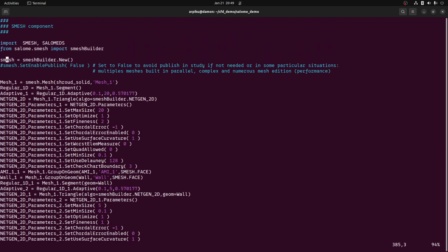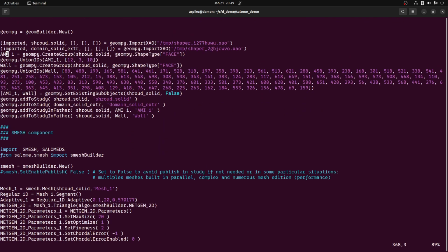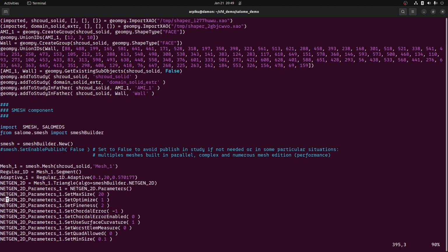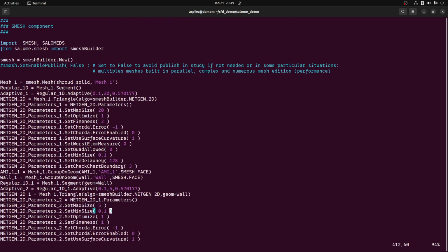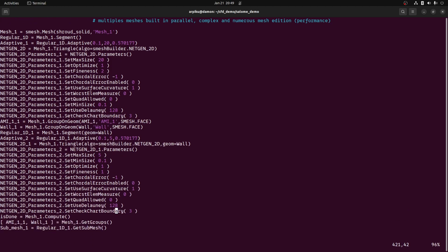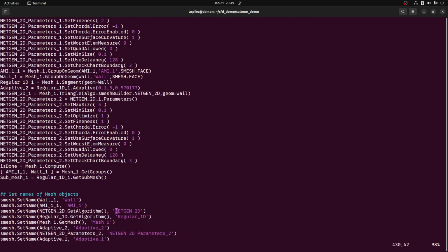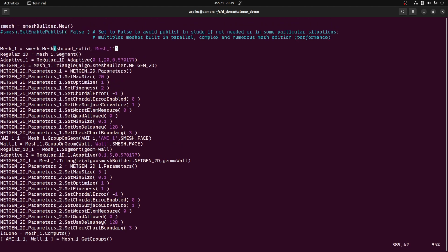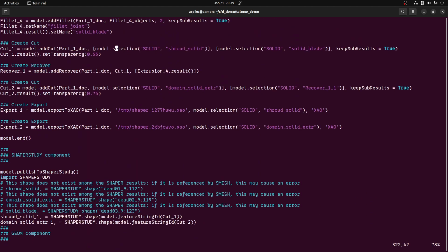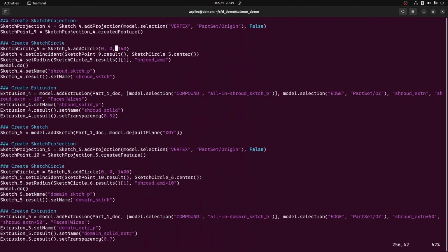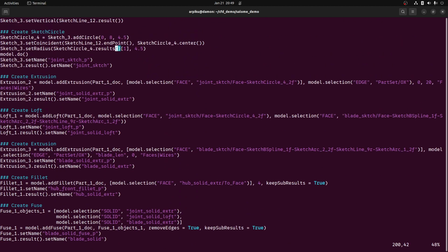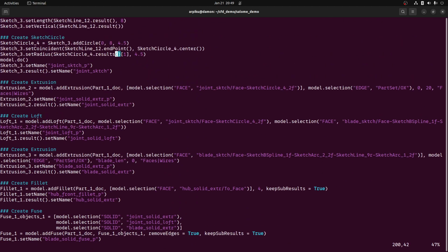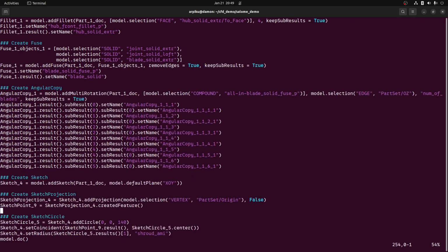And exactly as earlier, you can play around with the variables now. The parameters for the meshing are also defined through very simple Python functions, so you can change them around. So you can completely automate the process from the CAD model to the meshing part just using simple Python code.